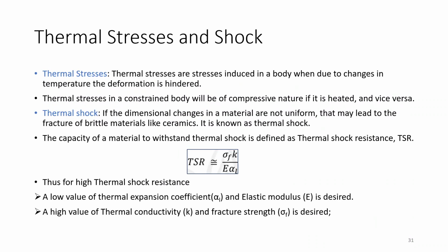Next is thermal stresses and shock. Thermal stresses are the stresses induced in a body when, due to changes in the temperature, the deformation is hindered. The thermal stresses in a constrained body will be of compressive nature if it is heated, and vice versa. Thermal shock: if the dimensional changes in a material are not uniform, that may lead to the fracture of brittle materials like ceramics, and it is known as thermal shock.